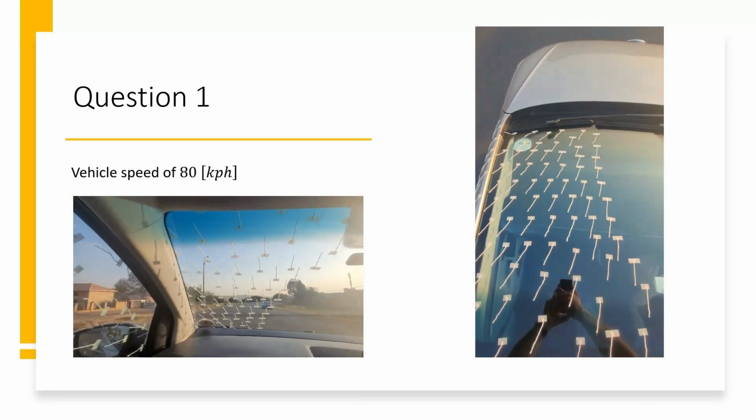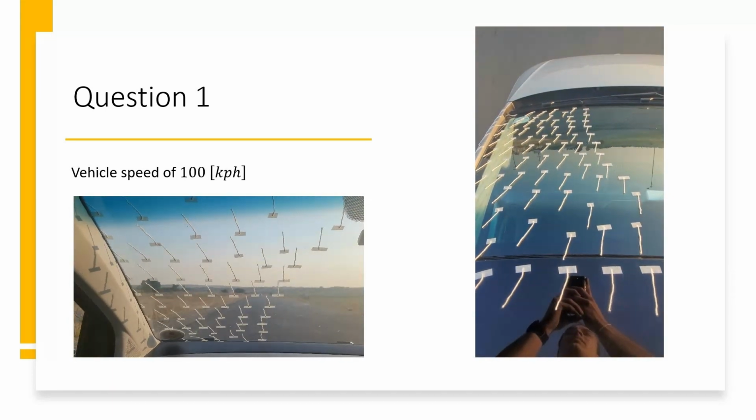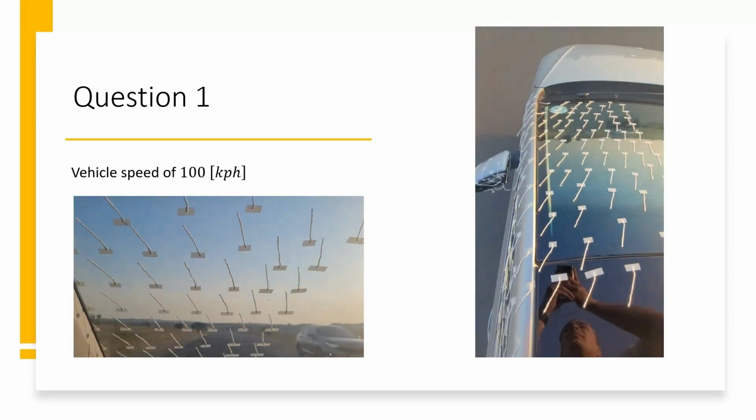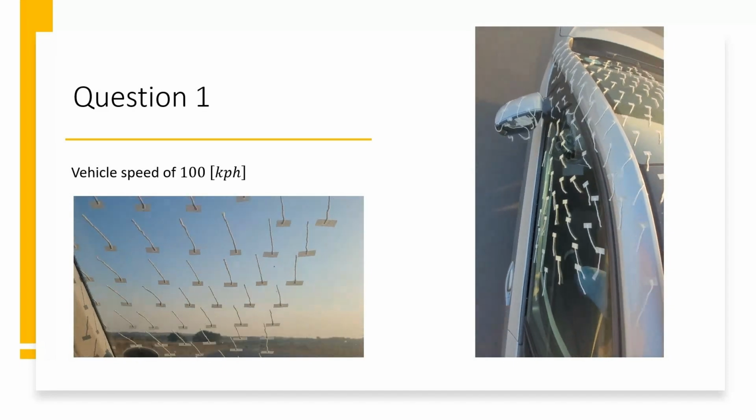As the flow moves over the A-pillar, the airflow separates at the sharply defined lines on the A-pillar. This can be seen due to the tufts on the A-pillar that are closer to the windshield not moving very much, and the tufts on the A-pillar furthest away from the windshield moving radically in different directions.